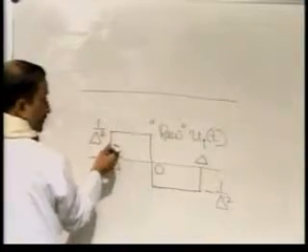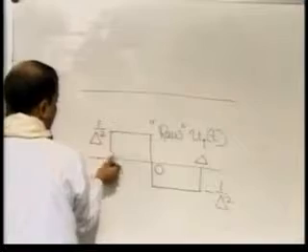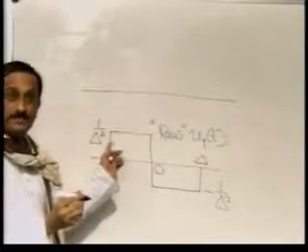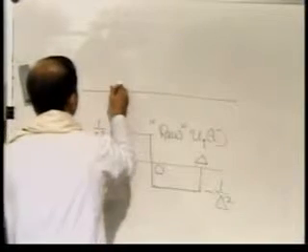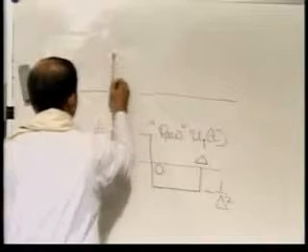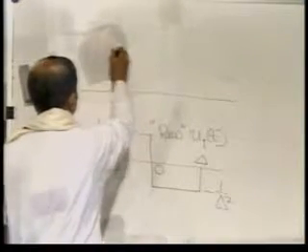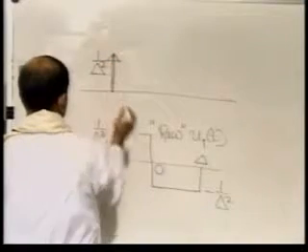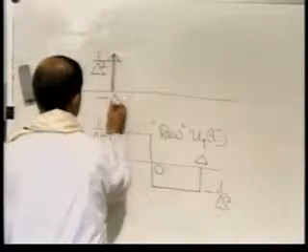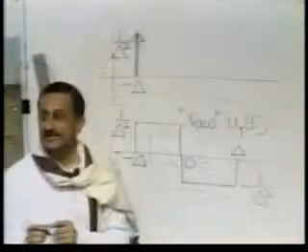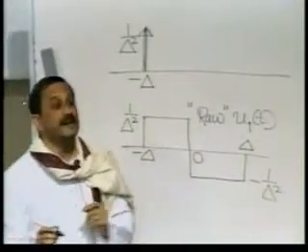So what will the derivative look like? Well, here you suddenly need to put in an area of 1 by delta squared, right? So you will have a positive impulse of strength 1 by delta squared here at minus delta. And at 0, you suddenly need to put in a negative area of 2 by delta squared.